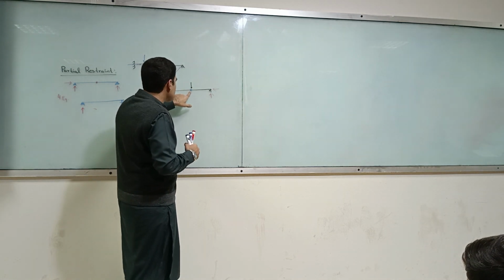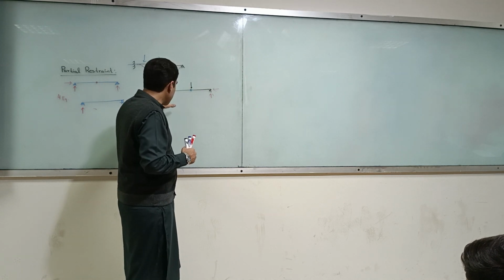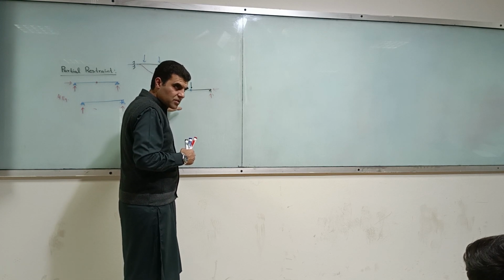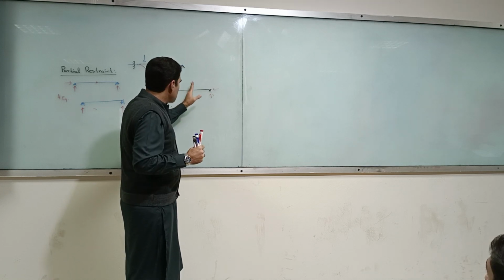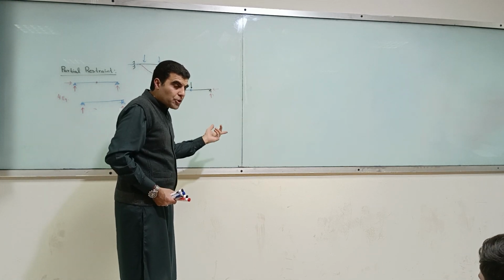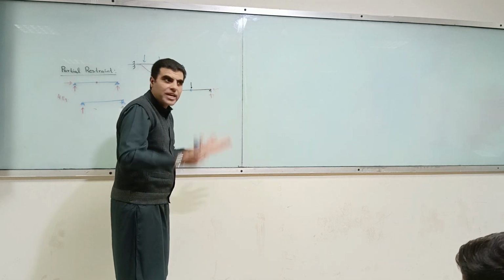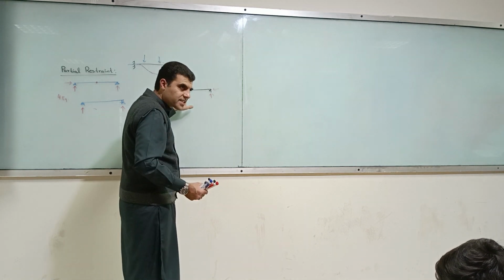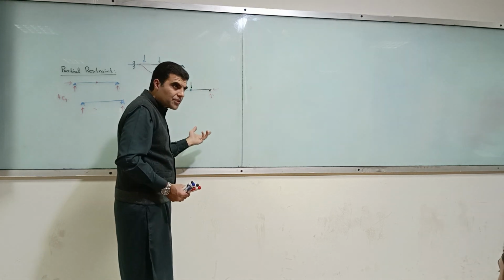This is the same thing. Look, in the middle you can have moments, but you can't have moment over here. Yes, sir, that is exactly what I am saying. This load will produce moment, and there is nothing to counter that. No, but how do you say the moment is balanced? Whatever moment it produces is balanced. The overall system moment would be balanced. Summation of all moments would be equal to 0. It is producing moment at this section, but if you draw a free body diagram, that moment will be balanced.